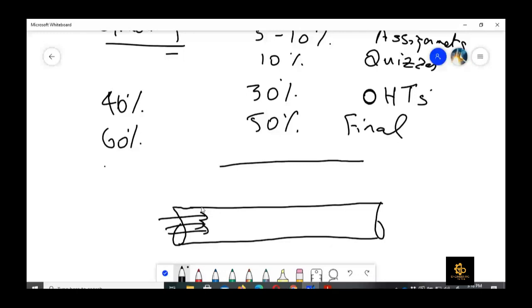That is called the drag force or shear force. We have to take it into account, because that force would drop the pressure along the flow. It means that the pressure at this end would be higher, and the pressure at the end of the pipe would be lower.